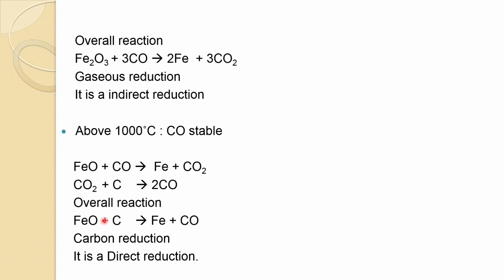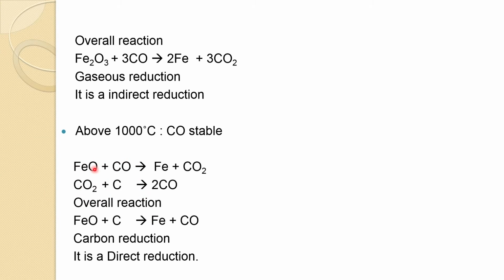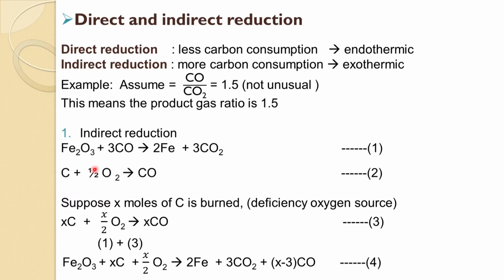This reaction may happen just near the base where liquid iron, in which you have some FeO present, travels onto the coke matrix in direct contact with the solid carbon, then this may occur, but this is negligible. So, mostly it is via the gaseous phase. And now we will talk quite a bit about direct and indirect reduction.